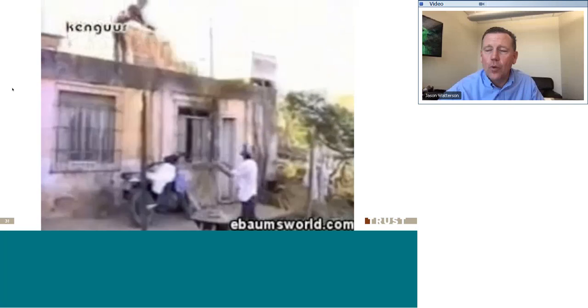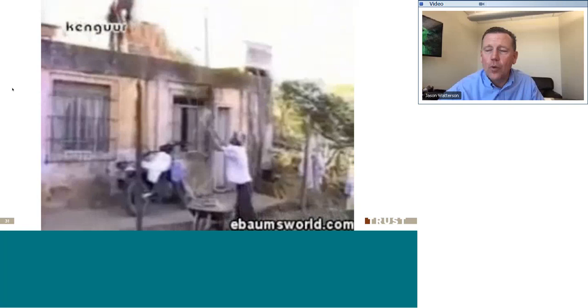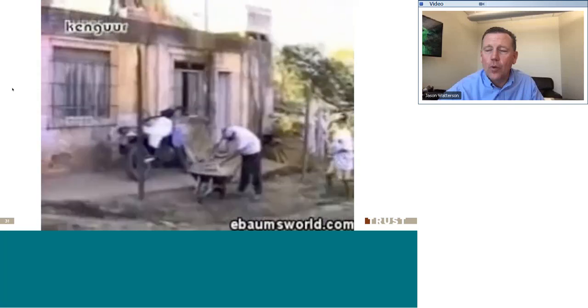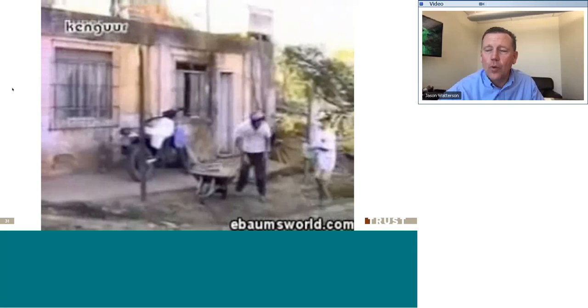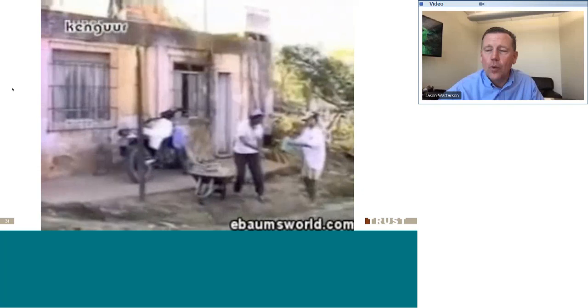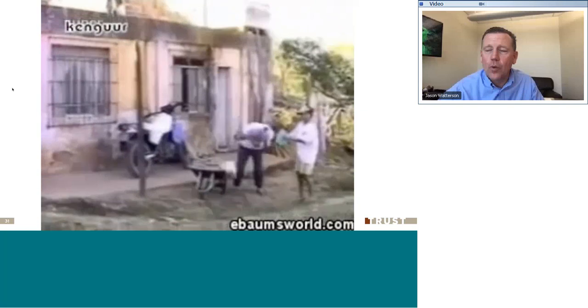And then here's some different classes. And this has changed in fairly recent years. Some of the OSHA documentation still uses the old terminology, but these are the appropriate types. Type G is general duty. Falling objects and up to 2,200 volts of electrical power. So this is not for linemen or people doing electrical transmission work. Type E is for electrical service. And so this is for higher voltage, up to 20,000 volts and falling objects. This is specifically for electrical workers.